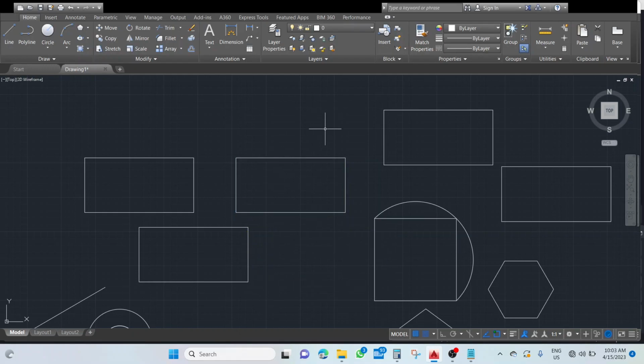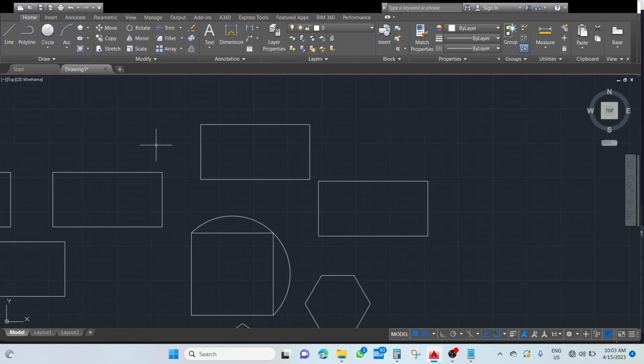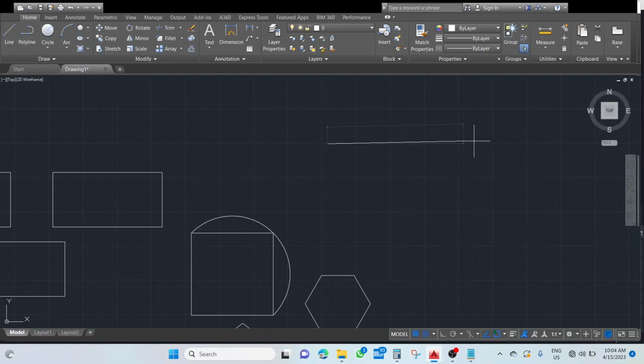Now next we have the rotate command. I will draw a rectangle over here using the line command to understand rotate. Line, start point, this first point. Ortho mode is off, so just press the F8 key on the keyboard. Now ortho mode is on. Right direction 200, downward direction 150, enter, left direction again 200, and upward direction 150. So this is the rectangle, just press escape.